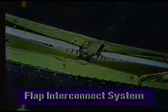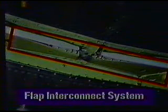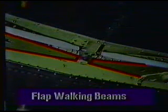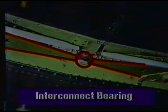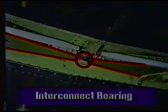The components that mechanically link the flaps together collectively are called the flap interconnect system. The major pivoting units are called flap walking beams. The units that connect the walking beam to the flaps are called the interconnect links. The bearing that connects the walking beams at the aircraft center line is called the interconnect bearing, or the walking beam bearing.